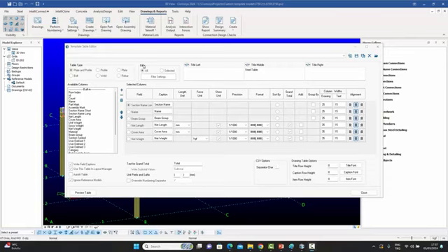If you're using this as a report generator, then once again you might need filters because you might not want to create tables or reports for the entire model, but only for certain parts of the model. You can use the filter, or you could use a selection-based filter. So you can directly select some things on the screen and create your report or your table accordingly.